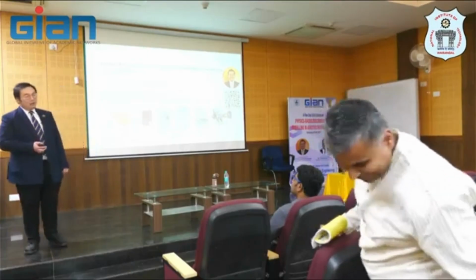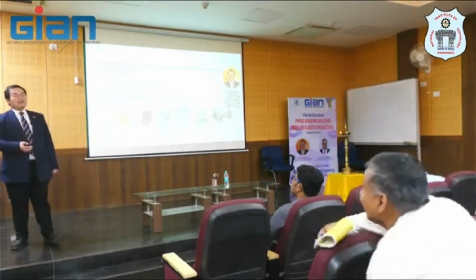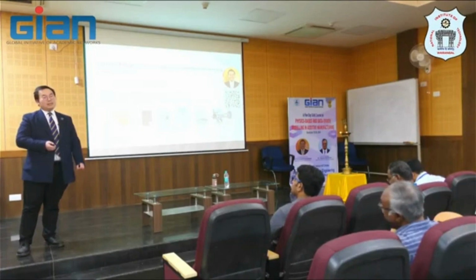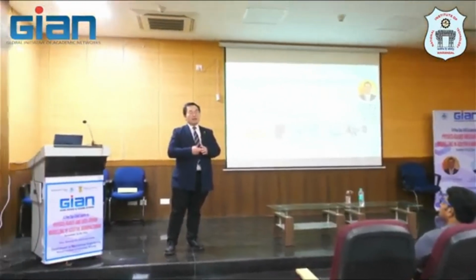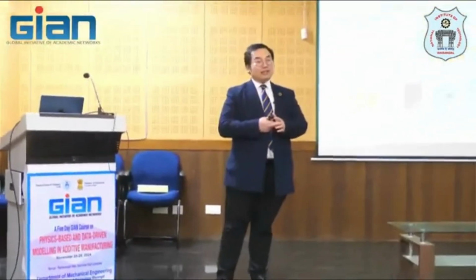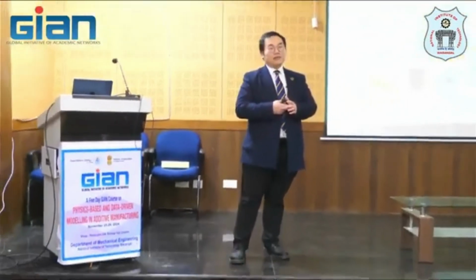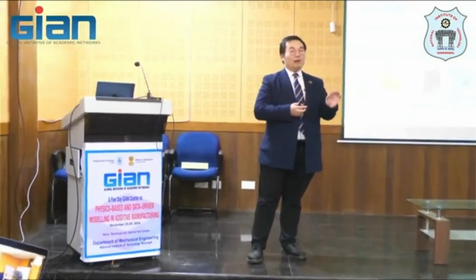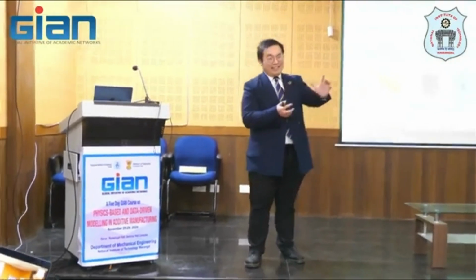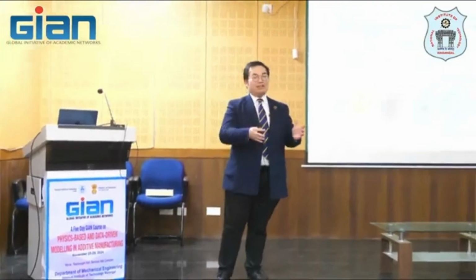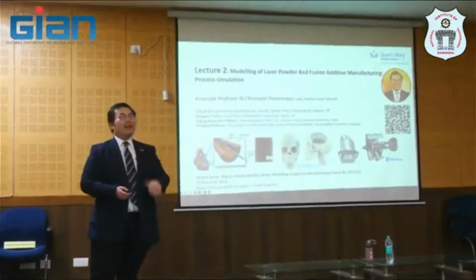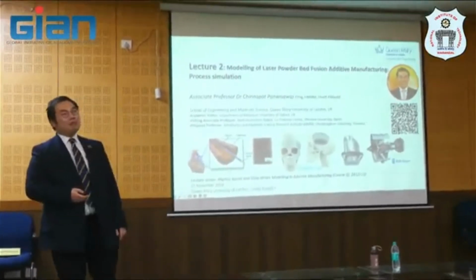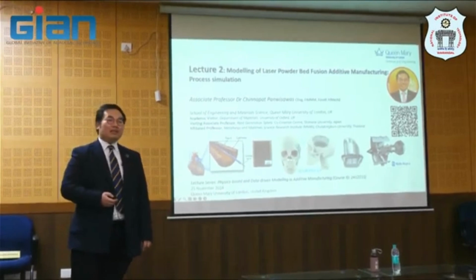That is the dream, but it still is too expensive compared with casting because electron beam is expensive. And mass production is even harder. Yeah, because investment casting is still expensive. Don't get me wrong, it's very expensive because it's cast one by one, right? Almost by hand, from the wax loss process until machining. But anyway, the property of single crystal is a lot better than polycrystal nickel-based superalloy.